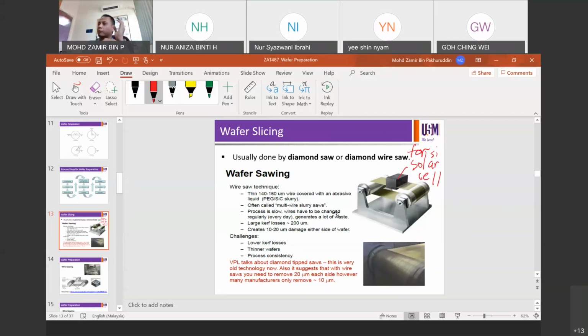Have you seen people cutting wood? Or if you go to a furniture shop, and you see a saw with big teeth, when you cut the wood it will produce dust. So that dust is actually a huge loss for silicon wafers. Imagine it's the very same wood as a silicon ingot. So it's called kerf loss. Down here, it's called kerf loss. So that means you cut the area, and you're going to lose so much dust. So that's called kerf loss.